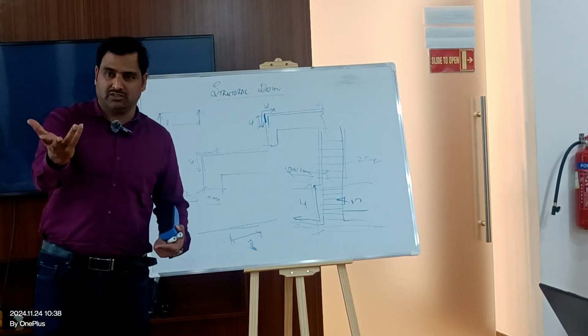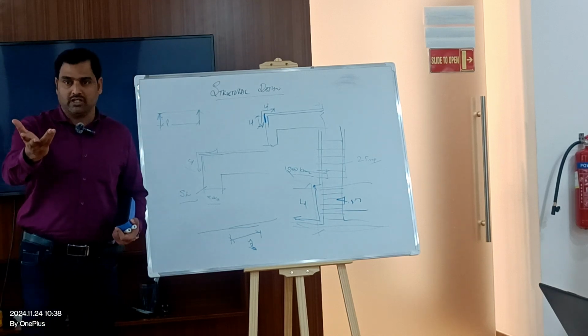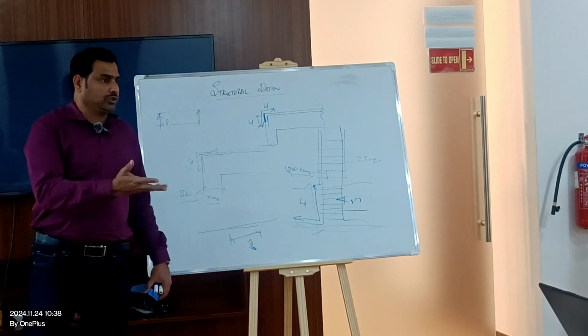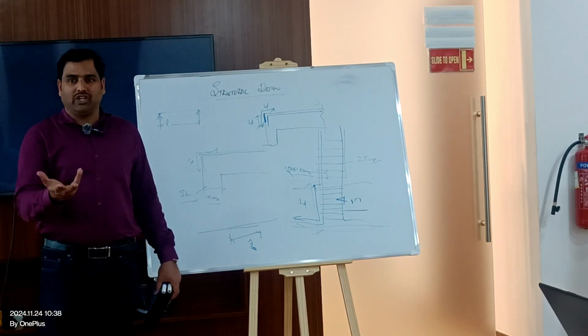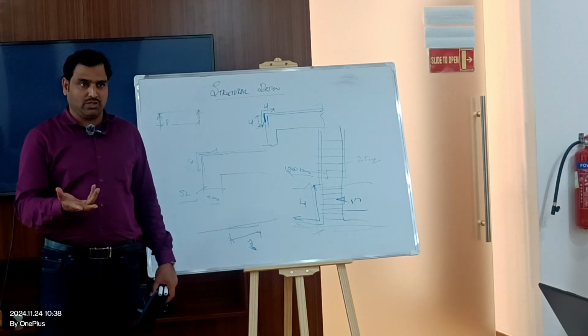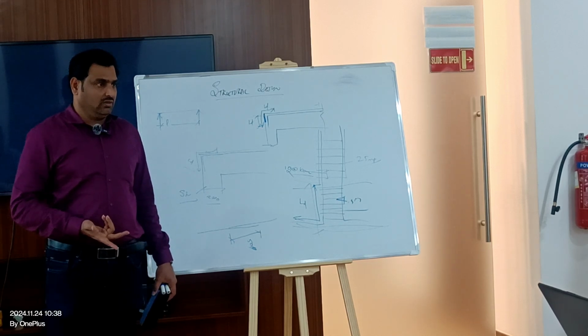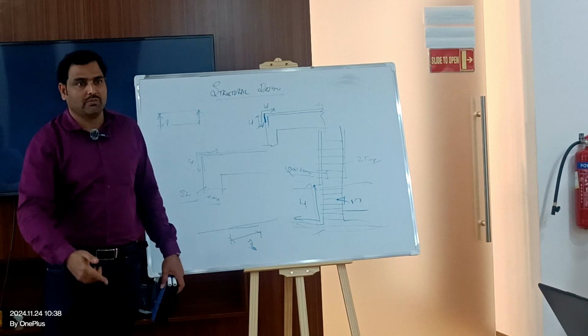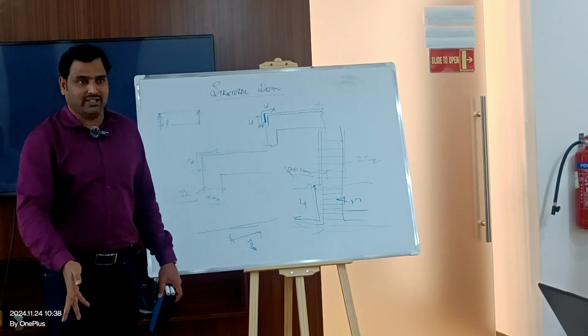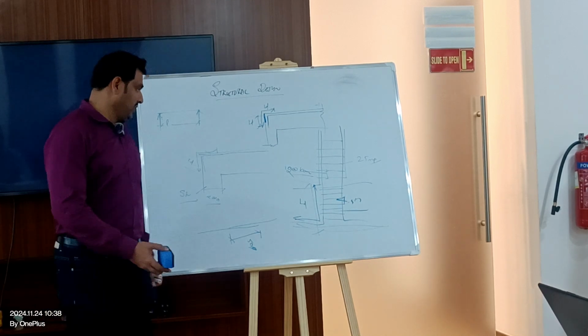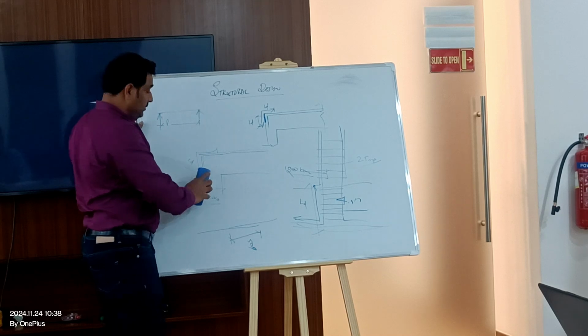You cannot really go even 300 also. It's very difficult; the site knows the difficulty. Even 30 centimeters is very difficult to drill. 15, 20, I believe 20 centimeters is okay to drill actually. And you will have so many constraints. Rebar will be there; if you touch the rebar, then you have to scan it. So many things are there. It's not easy.